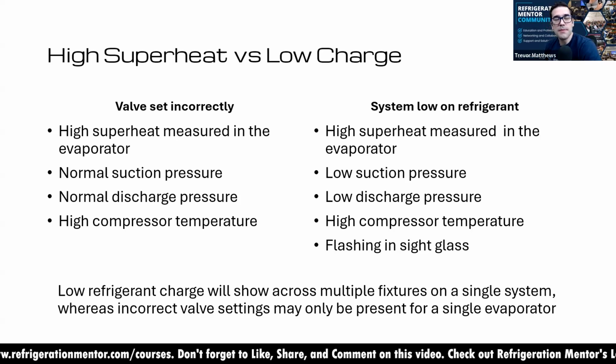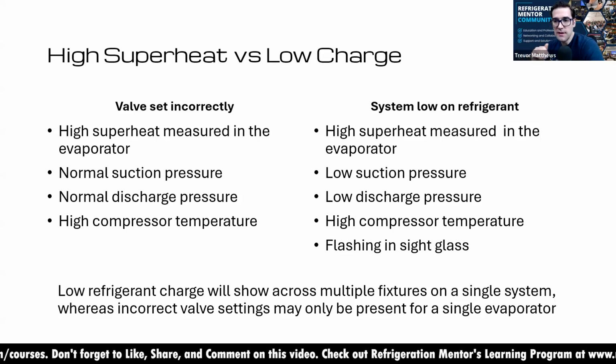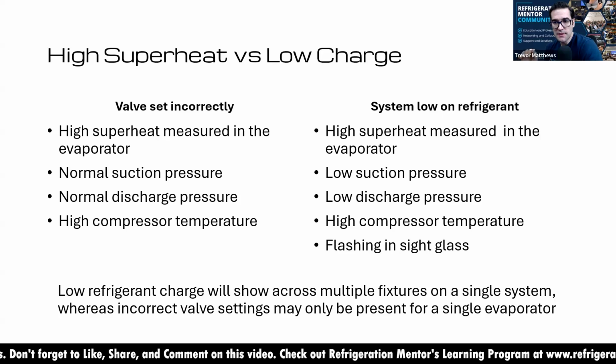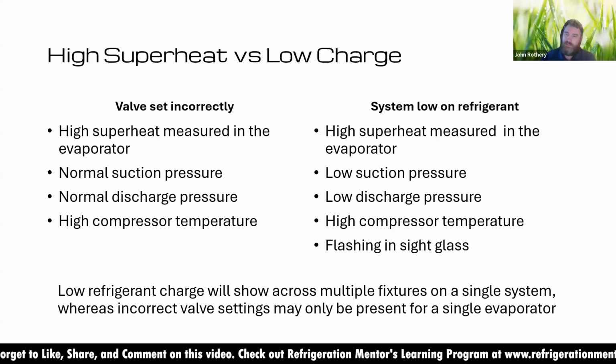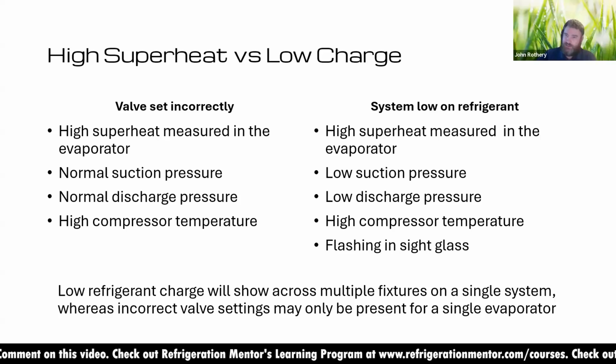So the flash gas bypass valve or the receiver valve is functioning, and all of a sudden power's killed. Potentially the valve could get out of line with where the controller thinks it is? Exactly. It doesn't know where it is, because if the power is not off long enough for the controller to drive that valve fully to zero, it can go out of calibration. So it's always worth checking they're calibrated.